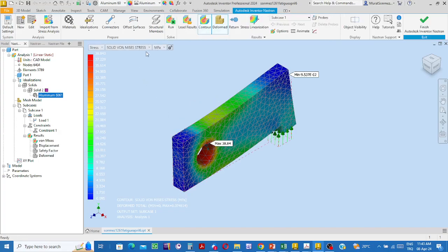Yes, maximum stress. In the vicinity of the surface of the hole, it is greater than the endurance limit, 39 megapascal. This means that while this object is being used, one day fatigue will occur. How much is the technical life of this object?